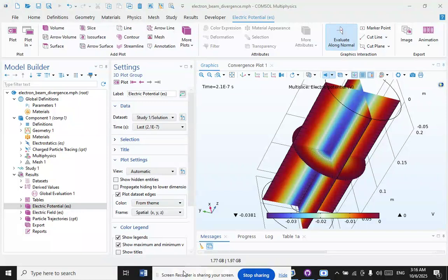In fact, the highly transient nature of the flows in EB welding and materials joining means that it is often impossible to accurately observe the flow phenomena experimentally. Mathematical models are also useful in obtaining accurate descriptions of the fabricated joints as the components enter into service, permitting the faithful prediction of safe operating limits and lifetime evolution of the joint region.